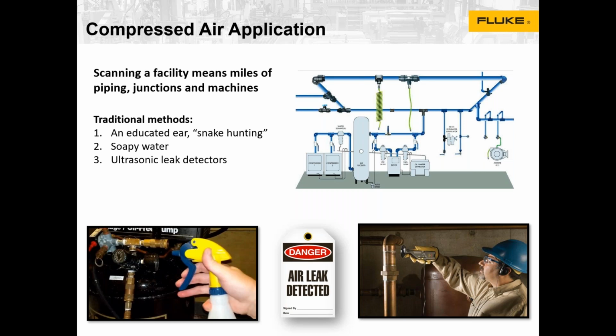I'm sure, I know I've done it looking for a leak in my car, or at least I used to. You can fill up a water bottle with water and soap, and you can spray all of the different joints or fittings or couplings, and when you've got bubbles coming back, that's because of the positive pressure coming from a leak.